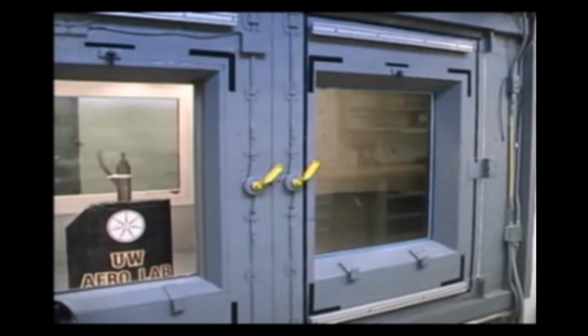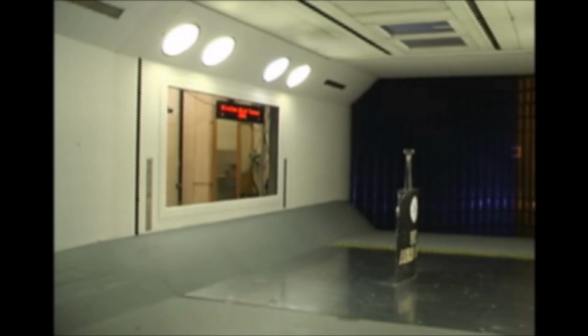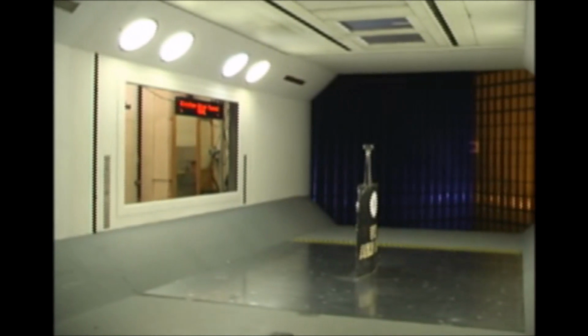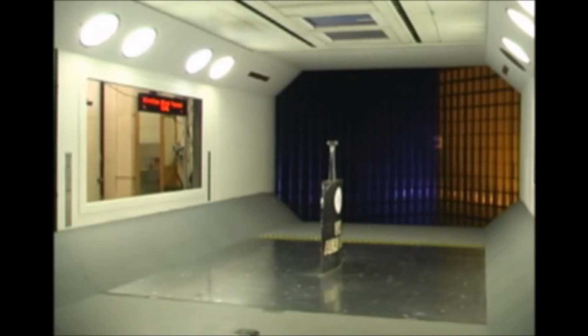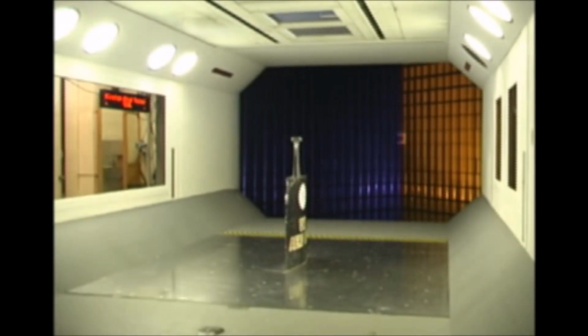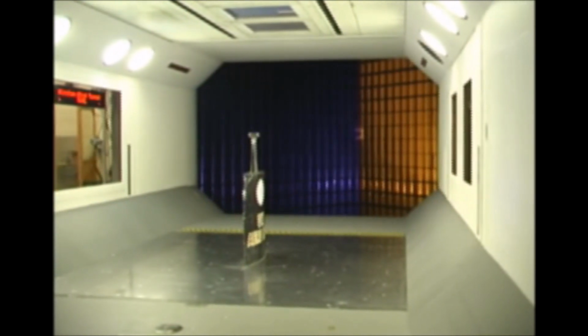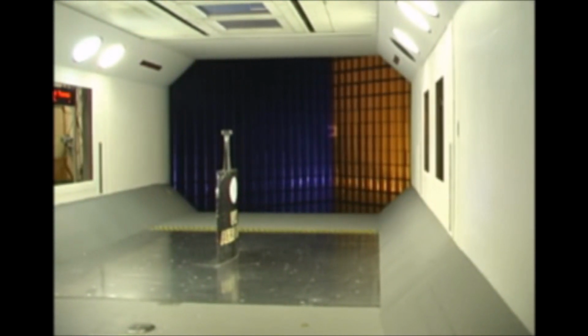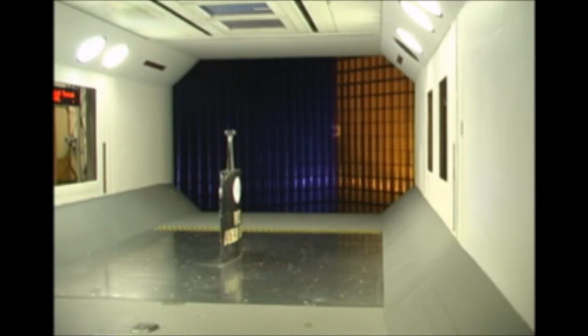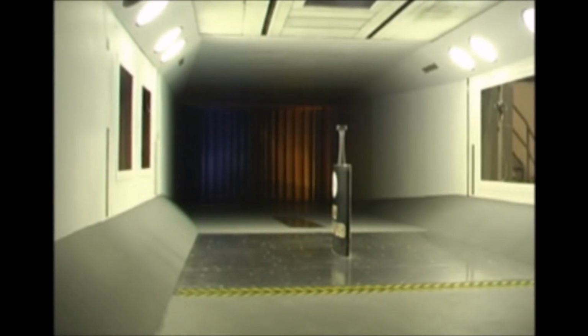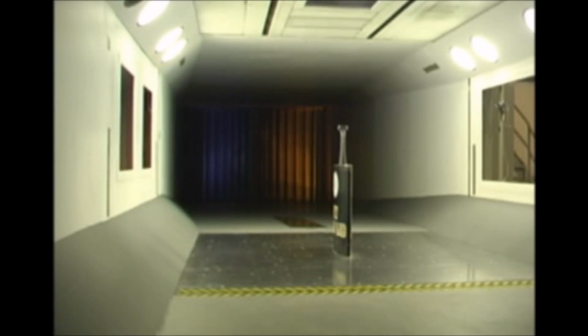The test section is 8 feet high, 12 feet wide, and 10 feet long, with fillets on all corners. The test section is vented to the atmosphere to keep the static pressure inside approximately equal to the ambient air. The lighting in the test section can be controlled to provide proper conditions for high-speed photography or other needs. The floor is made of removable aluminum plates that can be replaced with viewing windows to allow for observing the underside of the model. The model can also be viewed through interchangeable windows on the test section ceiling.